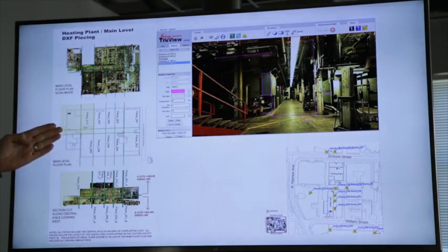where you can panoramically view around, but you're always looking at it from the perspective of the scanner. So you don't see the occlusions. You see exactly what you see. It looks like a 3D photo, but you can measure between any of the points there with accuracy of a few millimeters across all of that in 3 dimensions. And so that's a pretty useful tool for the guys in the field.